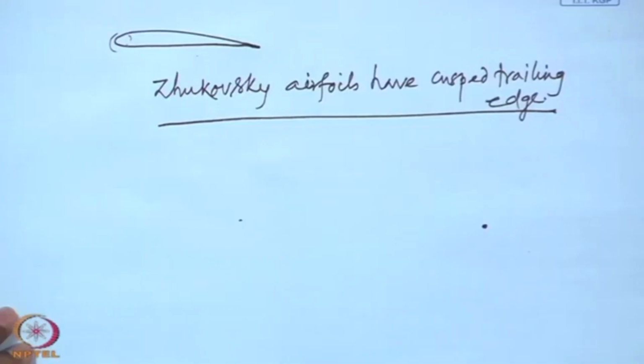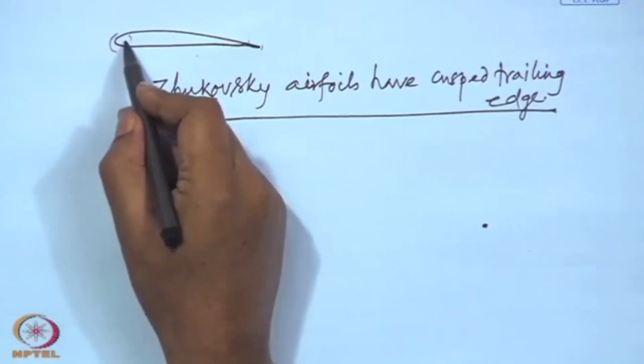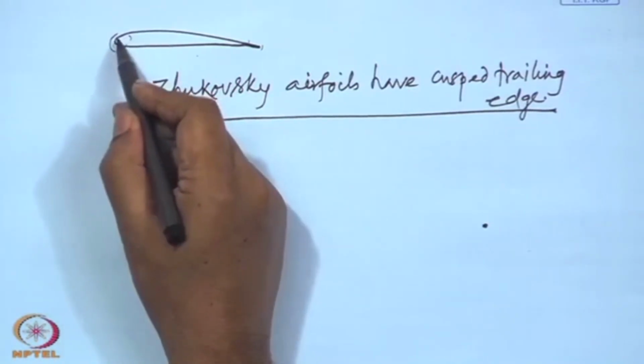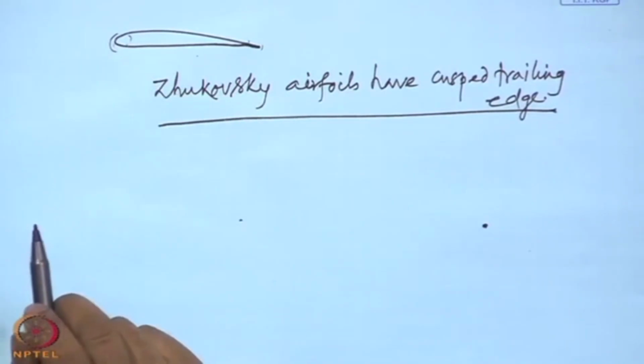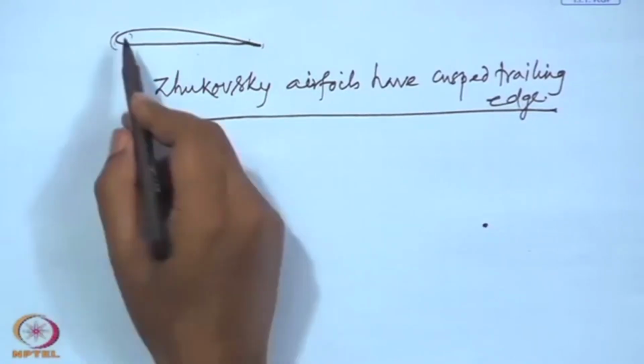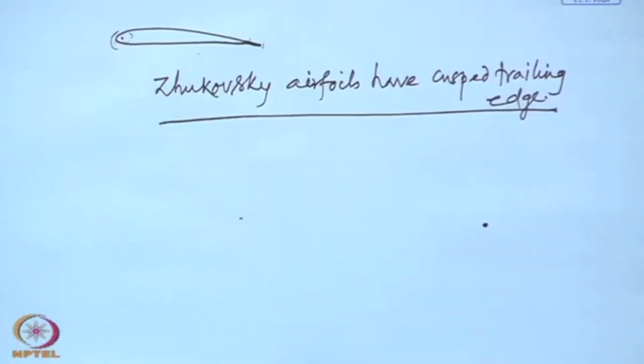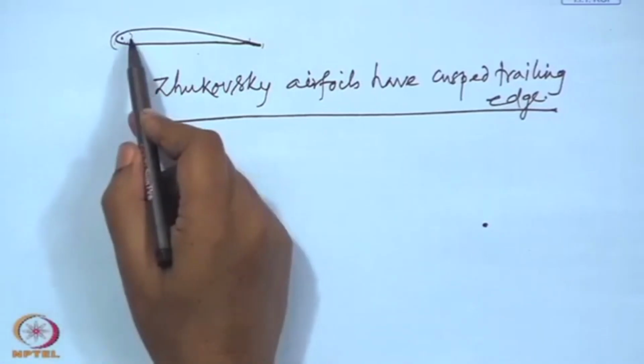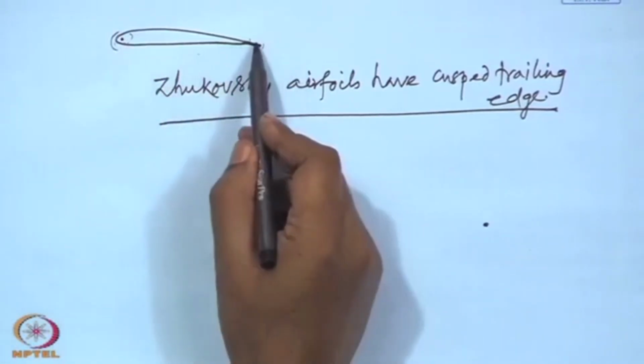We know this part is the leading edge part, we know this part is the trailing edge part, but which point is the leading edge point and which point is the trailing edge point, that may create a difficulty. That is given by the largest curvature in this, and the corresponding radius of curvature or the center of curvature, and similarly here also.